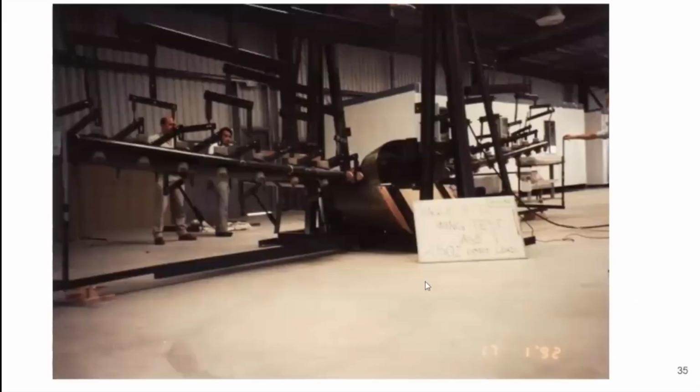So this is an example of Eagle, this Eagle aircraft, and this is a test. You can see there's a wing here, and we can see all the load applied to here, we call it fur tree. On this load here, we have put padding over the wing, and we have the fur tree here, and we calculate what will be the forces for each of the padding, simulate the load distribution over the wing, and we pull it up until the wing breaks. So you can see here 2.50 limit load. Eagle XTS wing test case 1, 250% limit load. So they go for 250% of limit load. And this is the early development of Eagle. I believe this is in 1992. You can see the photo here, 1992.